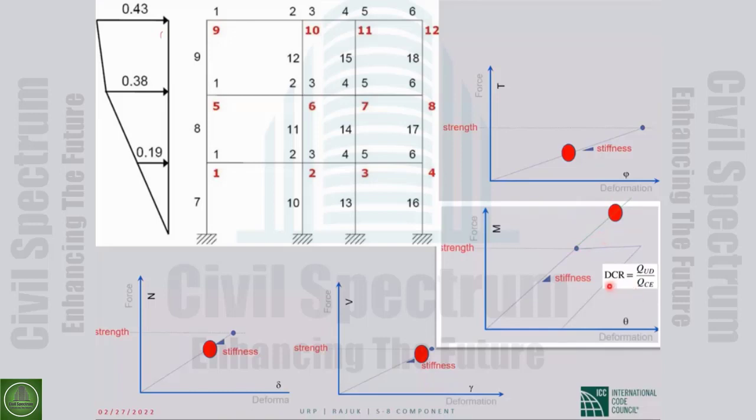So we use linear analysis. We can't really calculate the damage, but we use DCR, the demand divided by the capacity, so it shows how much damage. Only in deformation control parameters we accept some level of damage if it's not passing the limits, the m factors. But for others, for force control, it's easy.